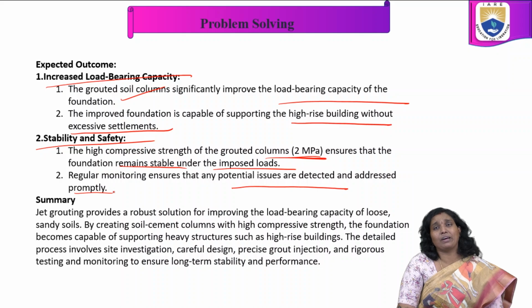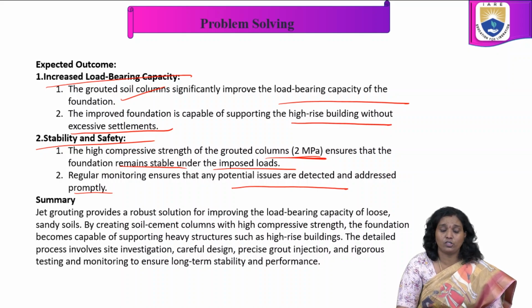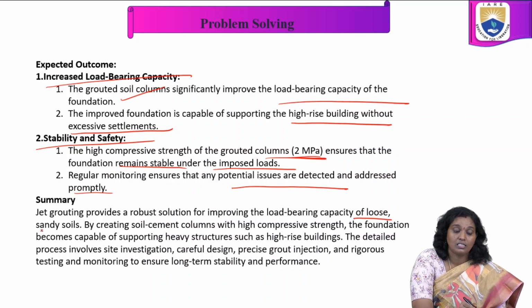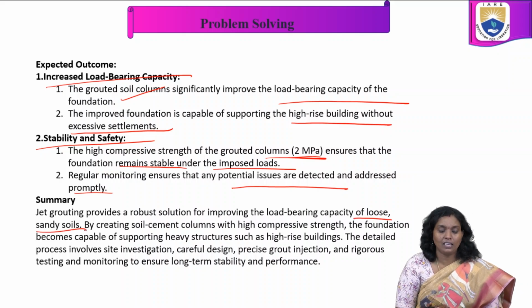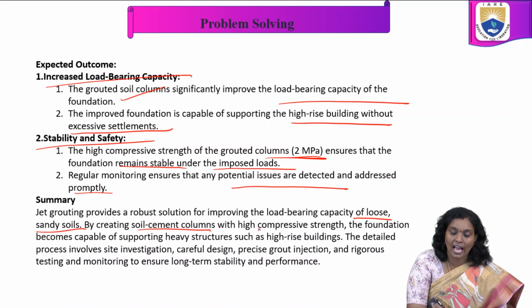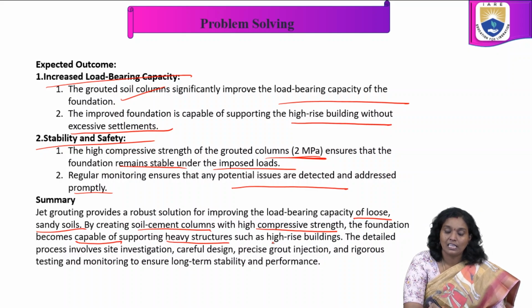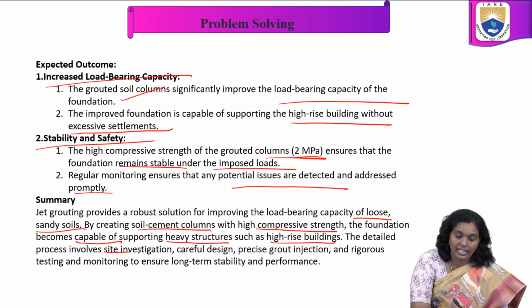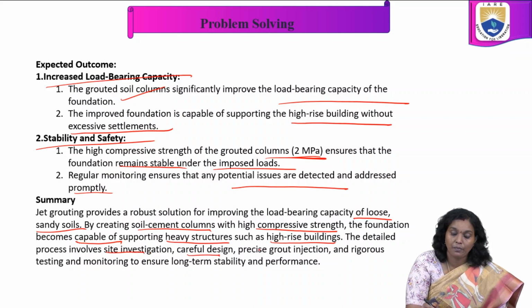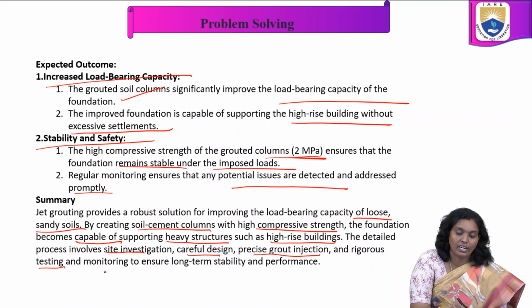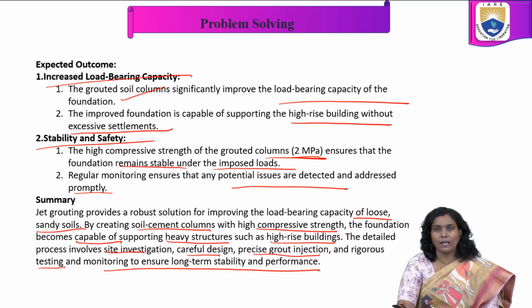So in overall summary, the jet grouting provides a solution for improving the load bearing capacity of the loose sandy soils by creating soil cement columns with high compressive strength. The foundation becomes capable of supporting heavy structures such as high-rise buildings. So the detailed process involves site investigation, careful design, precise grout injection and rigorous testing and monitoring to ensure the long-term stability and the performance.